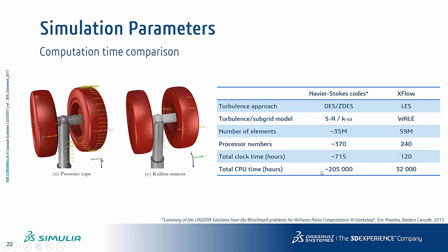So you can see Lattice-Boltzmann is very quick. We usually speak about an order of magnitude faster than Navier-Stokes codes for unsteady LES simulations, of course. If you compare a Navier-Stokes simulation running unsteady with LES turbulence modeling, it's very likely XFlow will go at least 5-10 times faster.